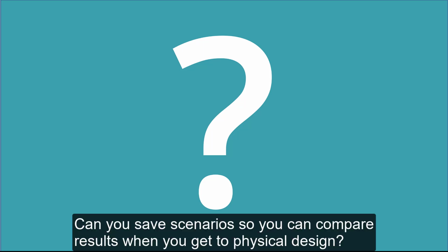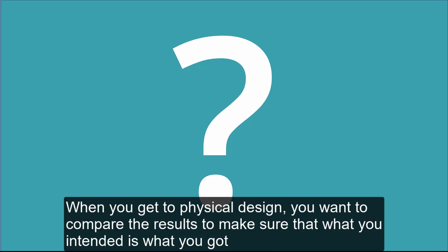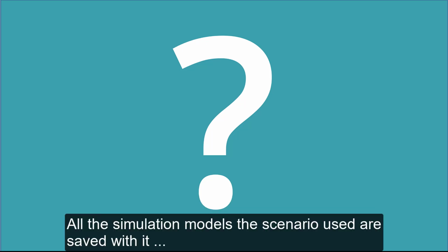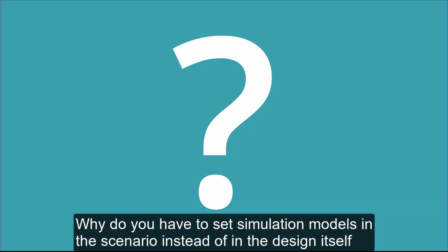Okay, some questions tend to arise from all this. Can you save scenarios so that you can compare results when you get to physical design? Well, the short answer to that is yes, and the long answer is yes and then some. When you get to physical design, you want to compare the results to make sure that what you intended is what you got. All the simulation models the scenario used are saved with it. And scenarios and simulation look and feel exactly the same when you get to PCB design, because they are exactly the same.